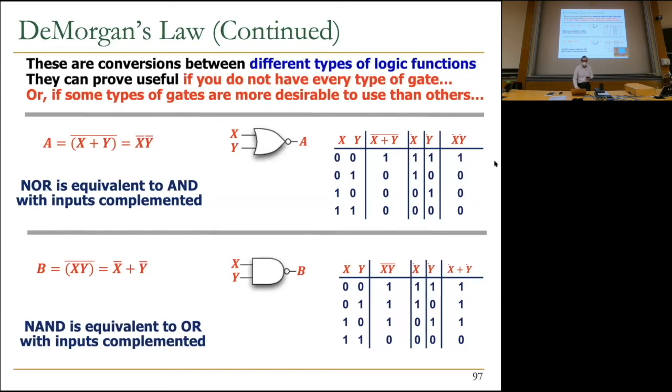You can actually follow the truth tables. This is the logical gate. If you don't have that gate, you apply De Morgan, you have this sort of gate. Oh, I have this gate. I can use it in your design. Or this gate is for some reason much faster because of how it operates in CMOS logic. Okay, so keep that in mind. This is also called bubble pushing. It's actually fun. If you see a bubble over here, push it to the inputs and change the gate type from OR to AND. And that's what you get. We call it bubble pushing.